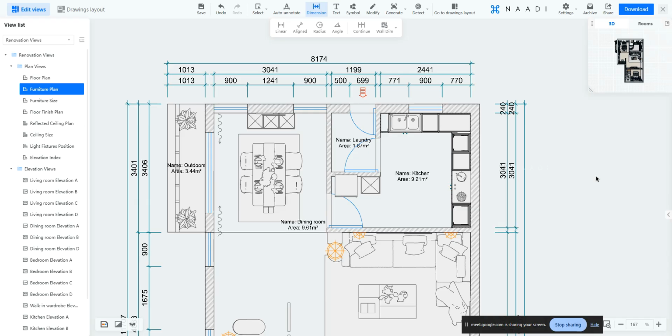In those cases, yes, you can manually add the dimension here too. There are certain annotations which you wanted in your drawing. In those cases, you have to manually add those annotations too. There are certain hatching which you need to do for a surface, especially for your cabinets. If you want to mention the finish differences in your shutters between your base cabinet, wall and anything of that sort, one of the common practices which the industry follows is to use hatch to represent the finish differences, right? Those hatches need to be done. So all these things, your missed dimensions, annotations, and hatches need to be done manually.